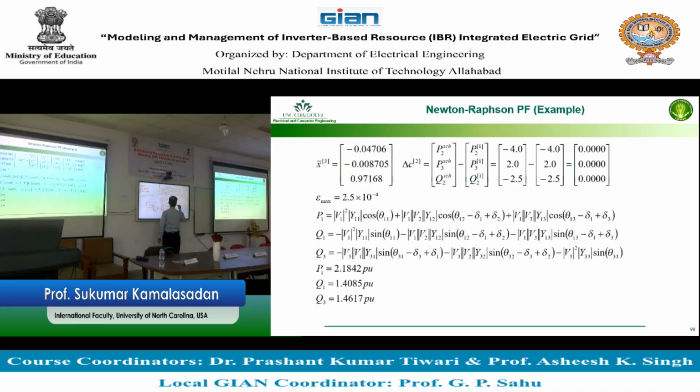I'm going to write it here. Step 1, run transmission system power flow, find voltage on bus 2.